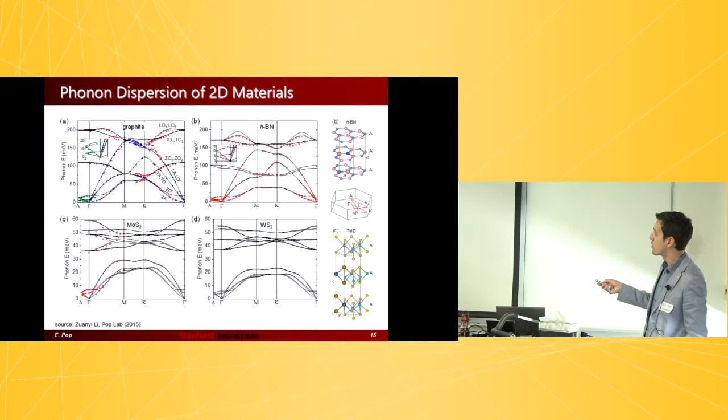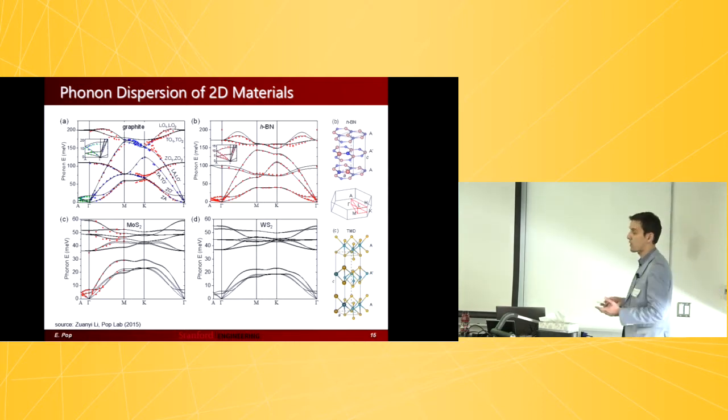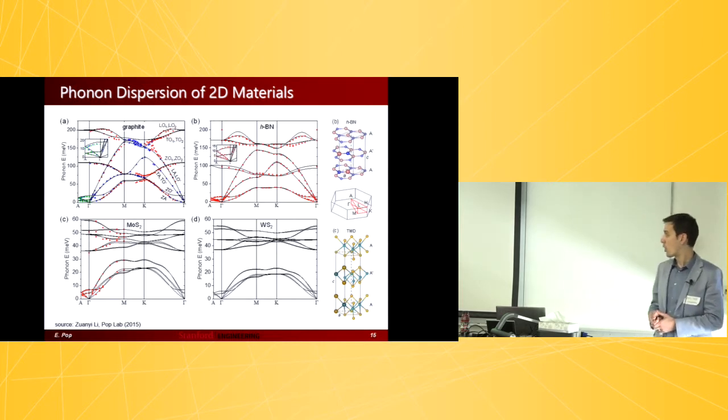Look how small those phonon modes are. So A, those are fully occupied at room temperature, and B, they have incredibly slow sound velocities, right? Which means, again, just intuitively looking at this, that the out-of-plane thermal conductivity component of these layered materials is going to be tiny, right? So you can already imagine that these materials are thermally very anisotropic, and I'll show you some numbers for those a little bit later on.